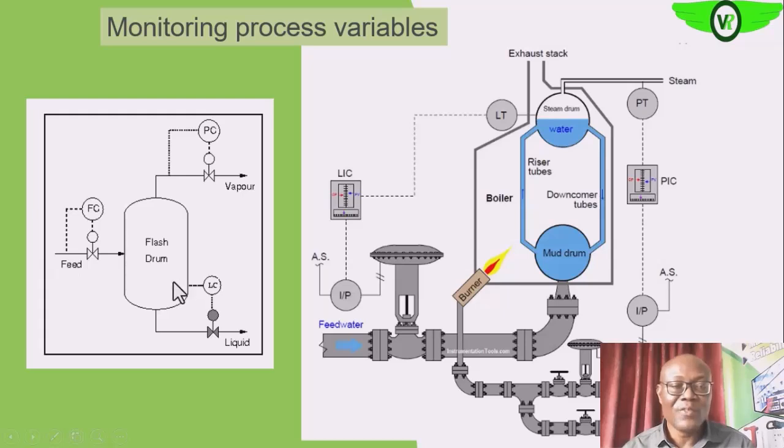Then the fluid that is settled down in the drum, we do not want it to go beyond a certain level. So you see that the process parameter level becomes a very important variable, because as the drum is filling, the level is changing, it will be increasing. As you are drawing out, the level is also going down.